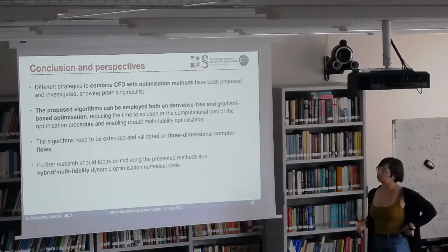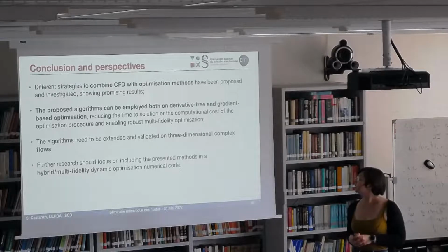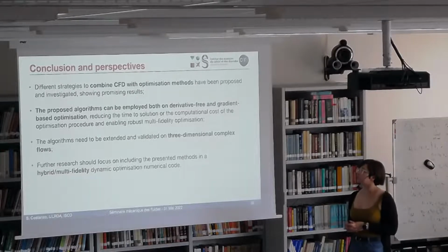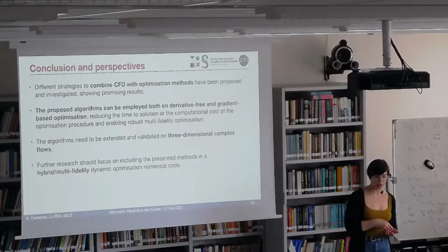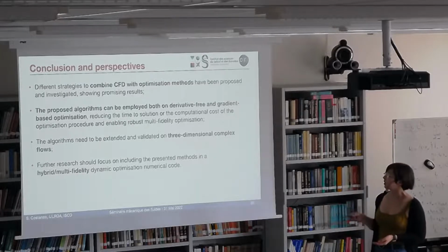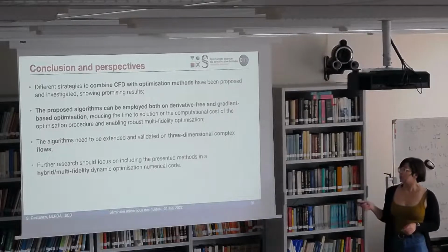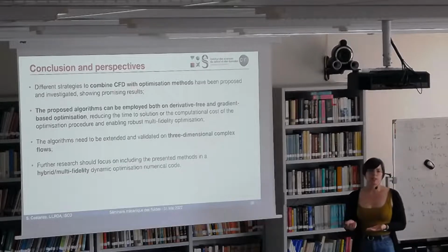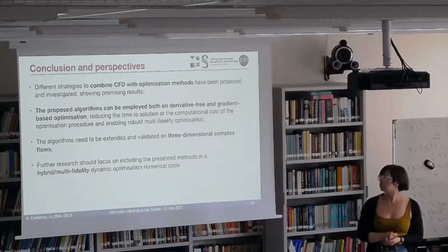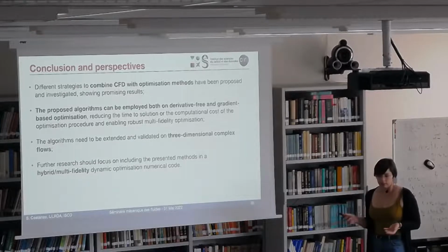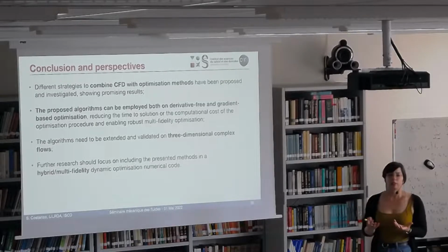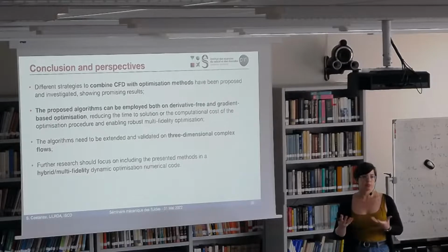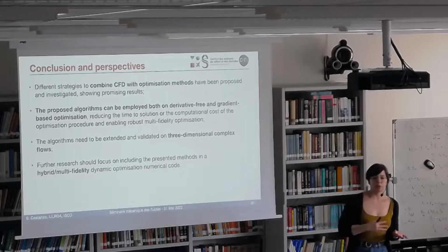And so, to close the talk, we were able to explore different strategies to combine CFD with optimization, both reducing computational time and computational cost, using low-fidelity models, enabling multi-fidelity optimization. Of course, this was just a developing phase. We have to test these algorithms and extend them to more complex configurations in 3 dimensions. And the very optimistic perspective is to have a code which is able to pick which optimization method to use, and whether to use reduced order models or not.